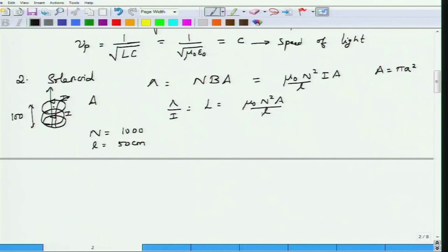Or maybe a better way of saying this is to talk about the capacitance of a coaxial cable which can easily run into 50 centimeters, and the capacitance of the small structure that you would have used in your laboratory. Those two concepts indicate the difference between localized capacitance and inductances versus distributed capacitance and inductances.